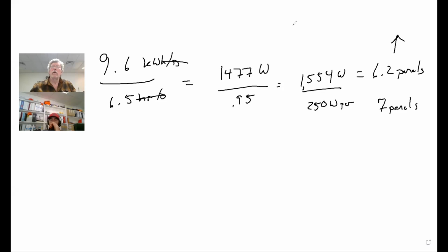So I'll jump into my whiteboard. All right, and so how do we do a battery bank problem? Well, first thing we need to know is the daily load. And we were told it's going to be 3 kW, so I'm going to say 3,000 watt hours per day.